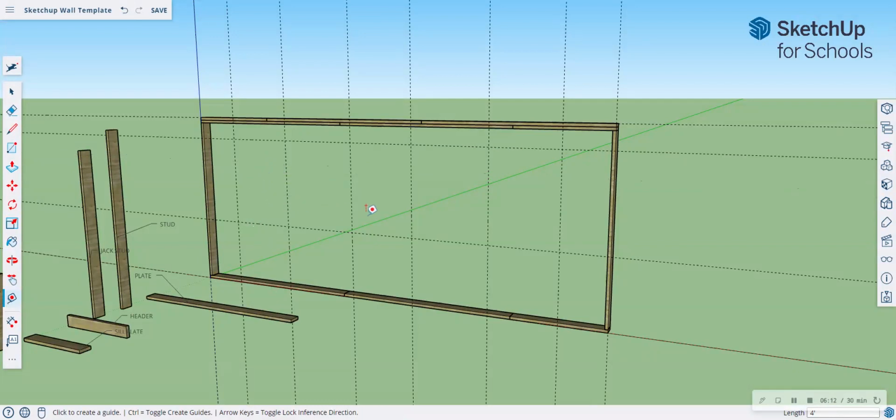And there we go. Now, what's handy here is that, and this is typical of most walls, the top of your window opening will be the same height or elevation as the top of your door opening. So right here in this box where my tool is moving around, that's our window opening. Here, again, follow the cursor, that tall opening, that's 3 feet plus 4 feet tall, 7 feet is our door opening. And then we have our window opening over here on the right. Okay, so that's how you create offsets to set up where your openings are going to be. And we will continue this on in the next video.